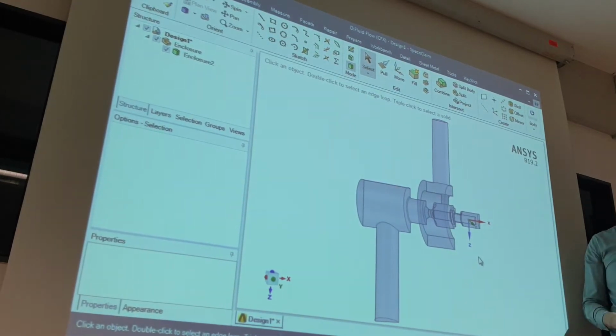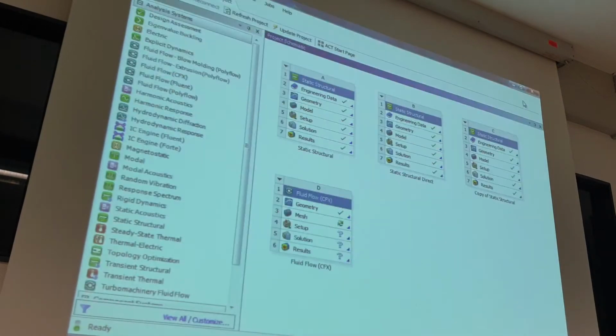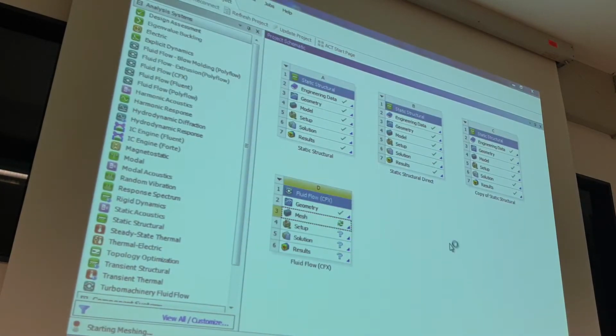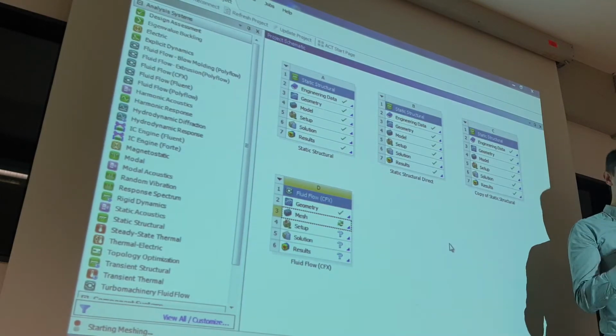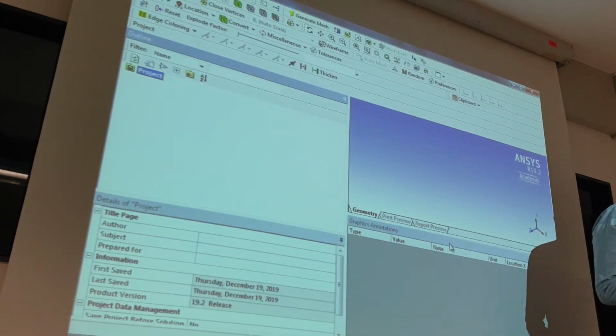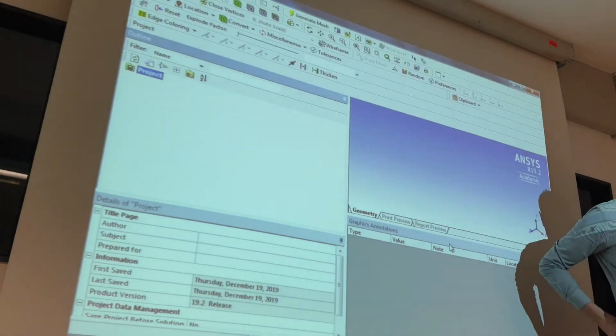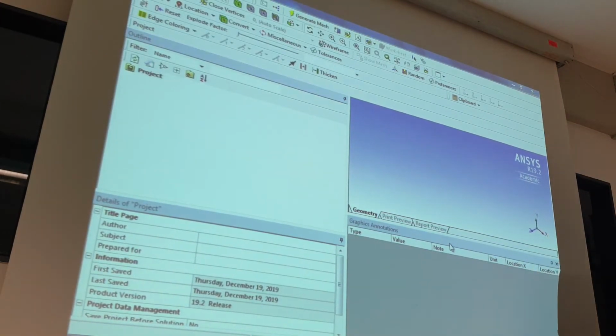It was all. And the third, very, very important thing is meshing. We need a special kind of meshing for flow simulation. Now the geometry is finished, we are opening our mesh tool, the same tool as mechanical, everything is the same, one-to-one, sweep, everything is the same. So the same strategy, but maybe more important for flow simulation to create hexa mesh. We have so many small gaps, we need to calculate them. Only with hexa mesh can we do it in a realistic time. So it's very important to do hexa mesh.